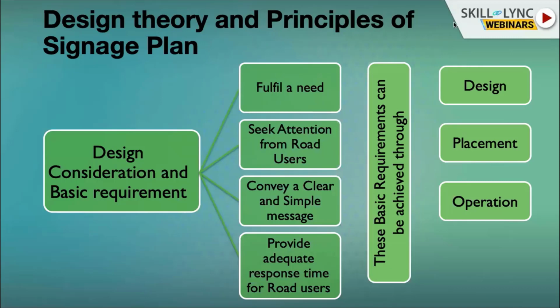Next comes the operational ability of the sign. This has to be checked by conducting random checks through the enforcement agencies, like for a speed limit sign placed. Unless it has random speed checks of the vehicles, it becomes non-operational over a period. Functional evaluation of these road signs should be done at regular periodic intervals or maybe even at random intervals, to see whether certain signs need to be changed to meet the current traffic.